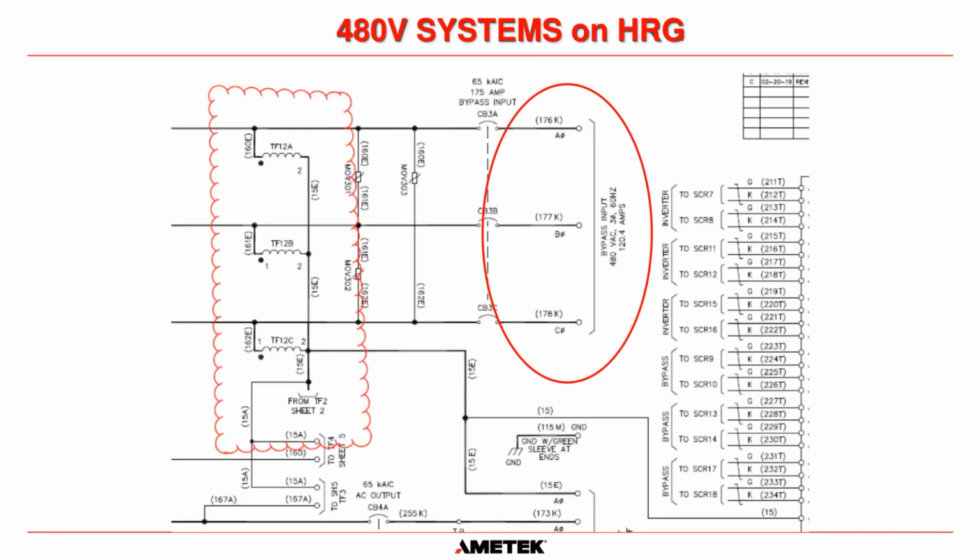So you can see all we have for this system here is A phase, B phase, and C phase. We do not run a neutral. And if you tell us that at the design stage of the UPS system, what we will do is, internal to the transformer, internal to the UPS, we will add this transformer here that creates a Y connection. It creates a neutral point within the UPS system for us. Okay?